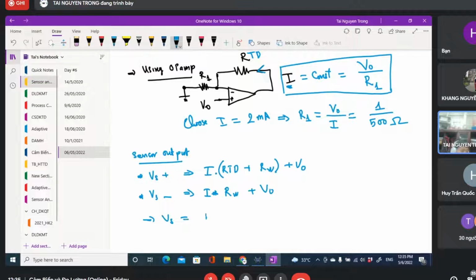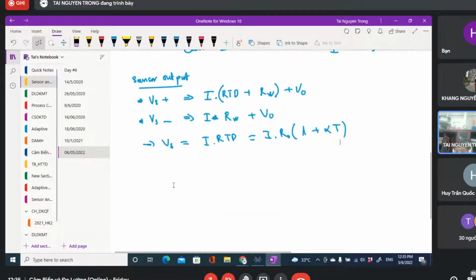Now we know the right hand side, right? So based on the Bode diagram here, we can determine the new frequency such that it satisfies this. And finally, we can compute the constant T based on alpha and the new crossover frequency. Do you remember, everyone?